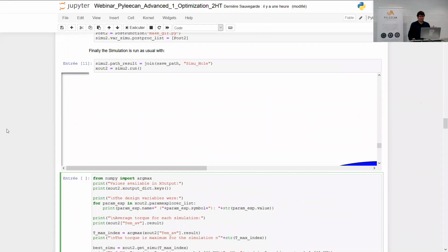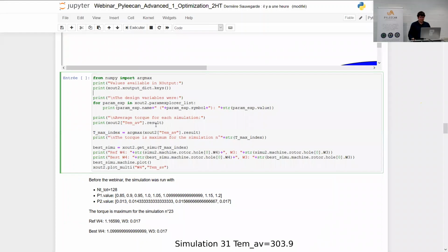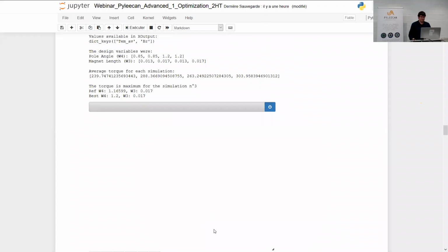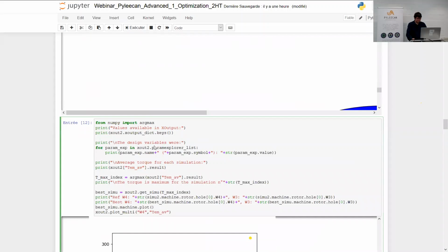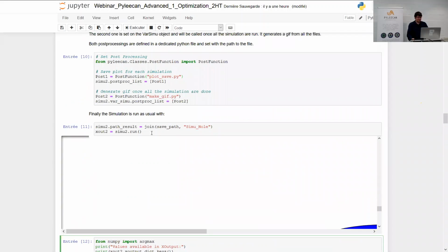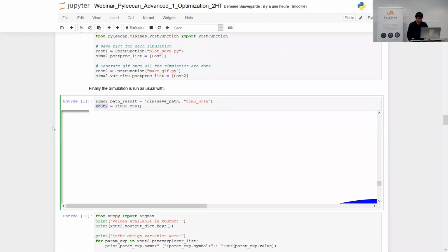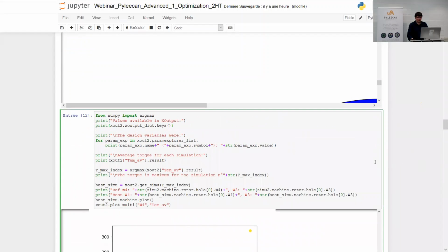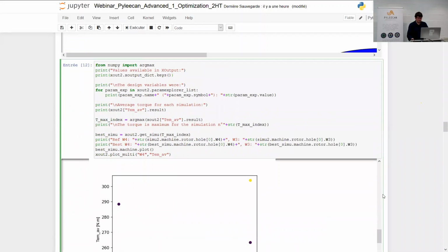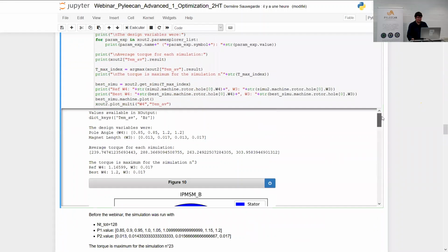So now I've run my simulation. Let's dive into what there is in the XOutput object. You can see that when I call run, it returns the XOutput. First, you need to know that we define the XOutput to be handled as a dictionary.